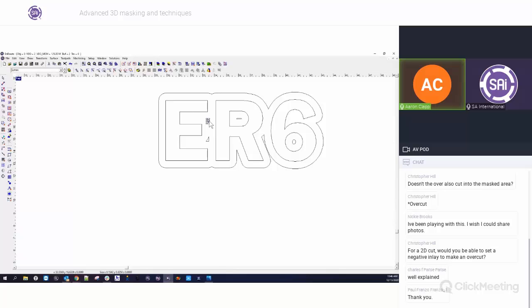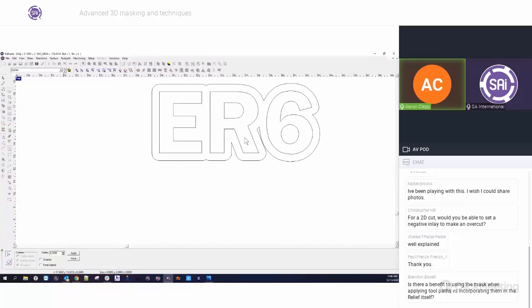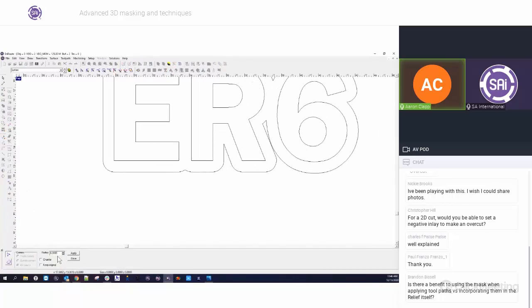This is too small. Those things will break apart. I deleted those. And then I went into my add fillets to contours. So basically just rounding off the corners of contours. And I put a 0.2 radius on all of my contours here and just hit apply.